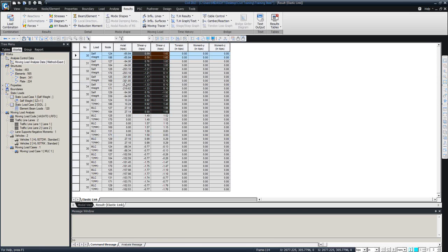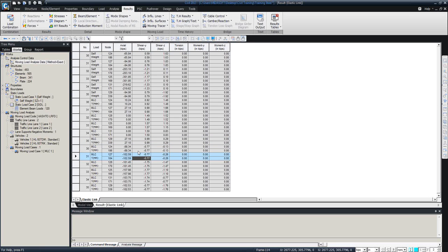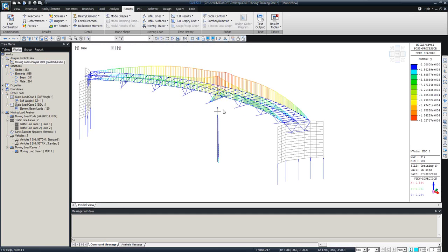So definitely the axial force, which is in the vertical direction for those bearings, is pretty high because I checked them based on the self weight and the moving loads. But you see the lateral loads also here. These are in the lateral directions, Y and Z, and then based on that you can select your bearing type, or you can design it as you want. All right, so that's also another type of output that we can get.